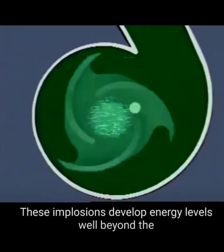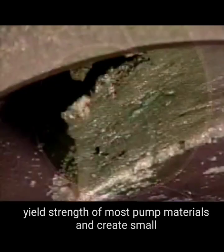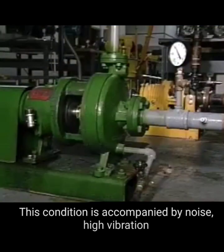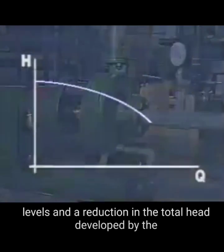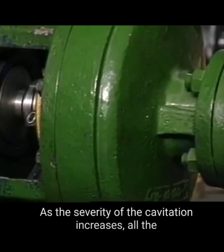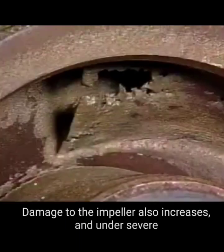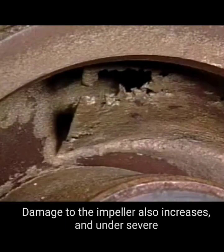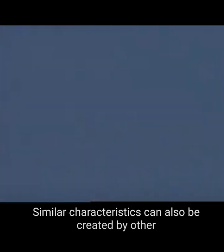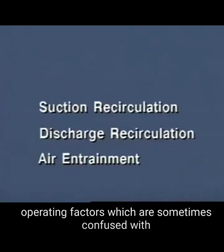These implosions develop energy levels well beyond the yield strength of most pump materials and create small cavities in the metal. This condition is accompanied by noise, high vibration levels, and a reduction in the total head developed by the pump. As the severity of the cavitation increases, all the effects will increase. Damage to the impeller also increases, and under severe conditions, damage will also extend to the casing. Similar characteristics can also be created by other operating factors, which are sometimes confused with cavitation.